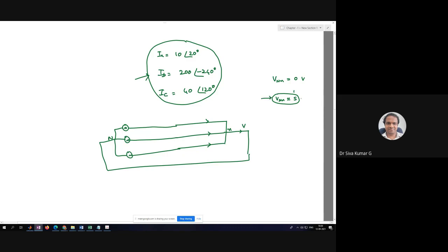They say this voltage should not be exceeded more than this particular voltage. If it is exceeded, the neutral voltage is going to shift because of the excess neutral current flowing because of the nature of the uneven loads. Because of that, the neutral will be loaded much more. Because of that, we will have the neutral voltage shift, and because of this reason, at the terminal point you will get unbalanced voltages of phase A, phase B, and phase C also.